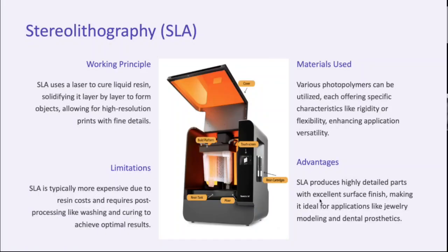If we go for FDM, we are working with thermoplastics, and after cooling, because of the temperatures, the part may sometimes shrink and have a little chance of dimensional deflections. But in SLA, the dimensions will be maintained 99.9% accurate, and it will have a good surface finish, as SLA works with a laser. We can define the print up to 50 microns.